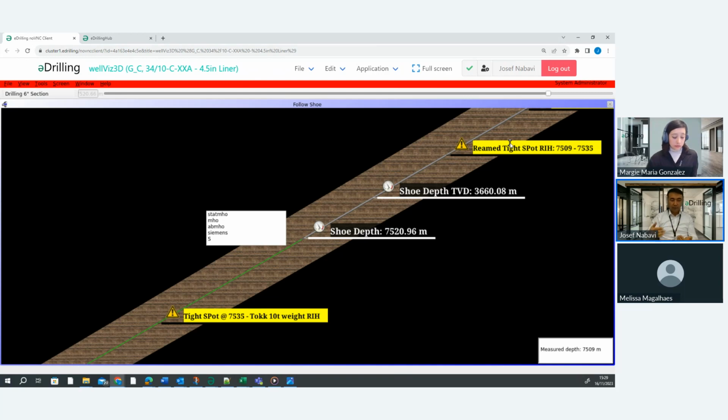Let's say during drilling the modeled SPP is a bit lower or a bit higher, and then the system runs for a 6 hour period. If you see everything is stable, after that it starts calibrating to the actual value. The same goes with ECD. And then when it has been calibrated, it just follows the same trend all the time. Any deviations after that will show you the risk in the well, show you something is not as it should be.